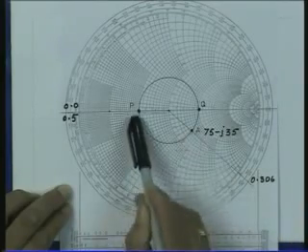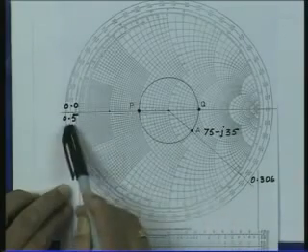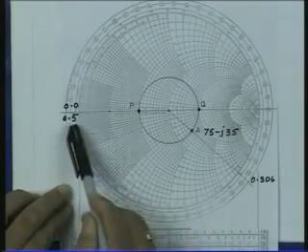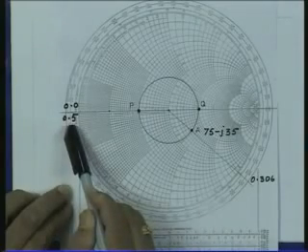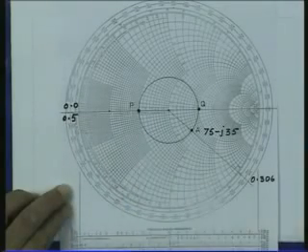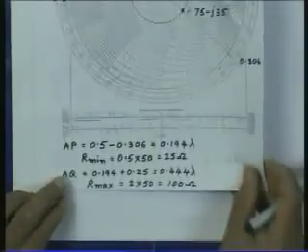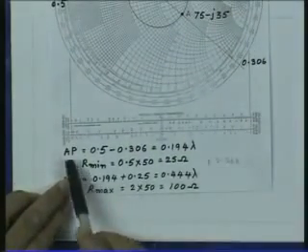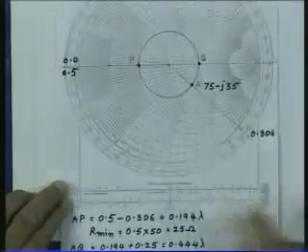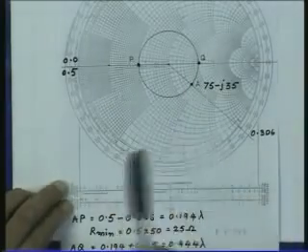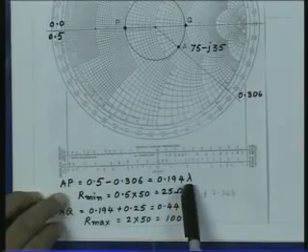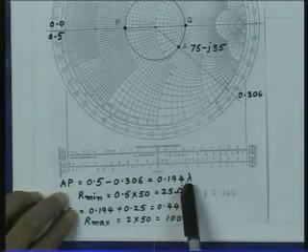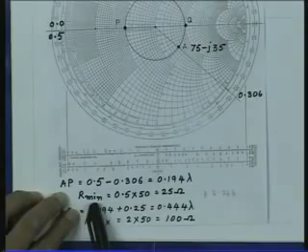If I move up to a point P which corresponds to 0.5 lambda, the difference of these two will tell me the length of the line which is to be introduced between the load and the quarter wave transformer. So, one possible solution is that if I take this length, then that length will be 0.194 lambda and the impedance to be matched will be R min,